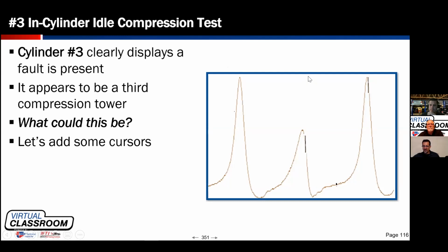So when I initially looked at that skewed pattern that showed the pressure pulse and the intake, I knew this was ignition strike number 1. I automatically assumed this was intake pulse number 1, when in fact intake pulse number 1 was way over here. So whoever asked that question, does that make sense what I just said? Why it's offset 360 degrees?